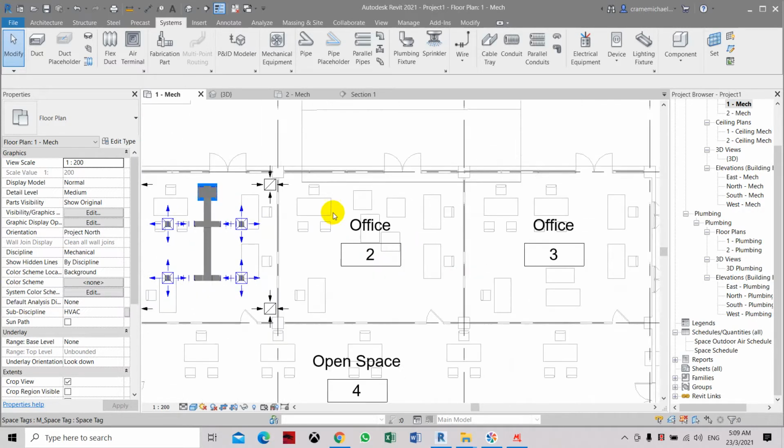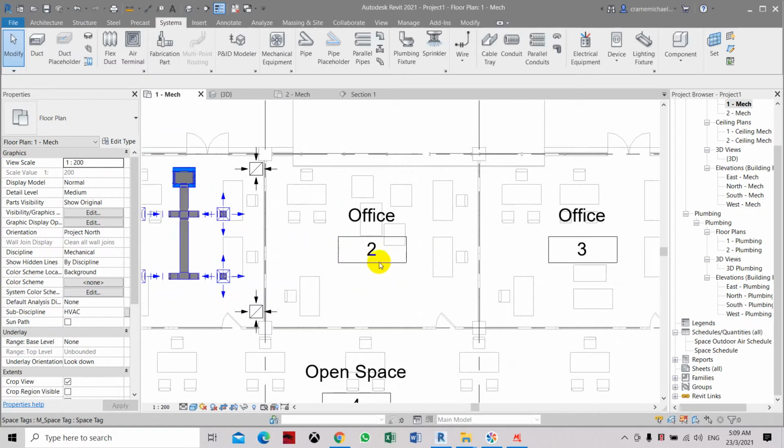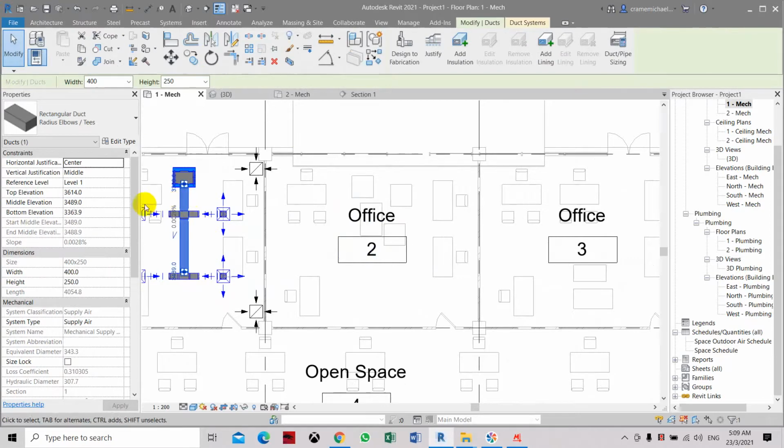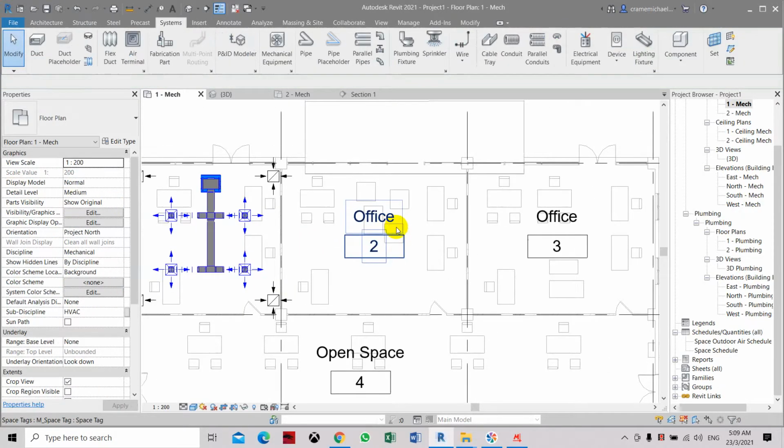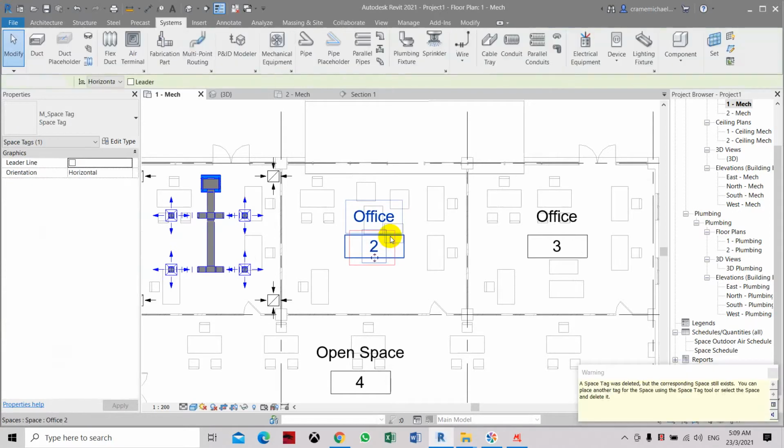Here we're going to also create the ductwork system, but we're going to use manual. We're going to do it manually by using the system tools and the duct layout tools. So this one was created automatically. The duct size here is about 400 by 250 millimeter. Okay, let's do the same layout.